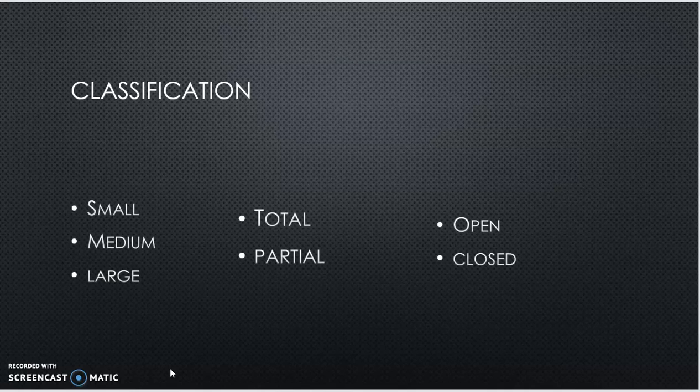Whereas in closed prefabrication, the manufacturer will produce components which are required by your project. So now if you're going for a house, you cannot go for closed prefabrication because no company is going to produce elements only for one house. Closed system of prefabrication is basically used for the projects where the plans are repetitive.